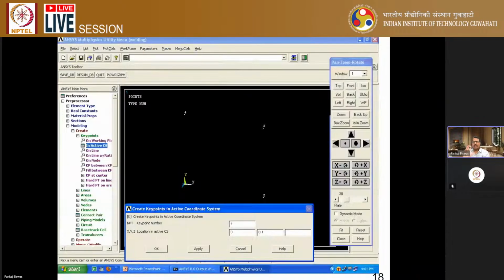So here, first of all, I am showing you how to make a model. For making a model, I have shown very simple steps here. You can start the modeling part from the corner point of the structure. First you need to define that point, or you can say key point. By this key point you can draw a line. That line can be a straight line or a curved line. By line you can draw an area. By area you can make a volume. So how, from scratch, from a coordinate point, you can develop a final geometry, that related information I'll give here.